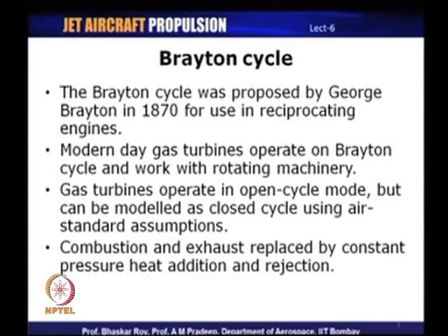One of the main differences between the gas turbines and the basic thermodynamic cycle is that the gas turbines operate in an open cycle mode, whereas the Brayton cycle that we shall discuss today is basically a closed cycle system. But you can still model the gas turbine engines, even though they are open cycle, as closed cycle using the air standard assumptions.